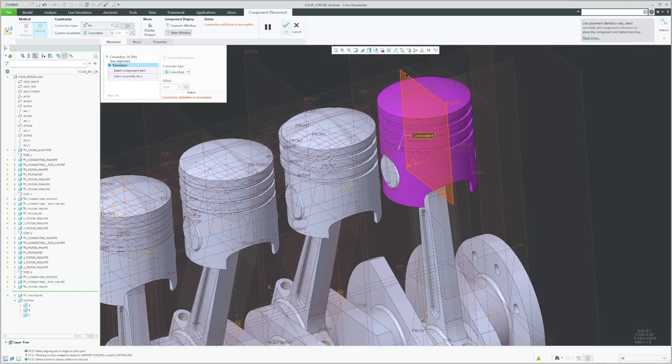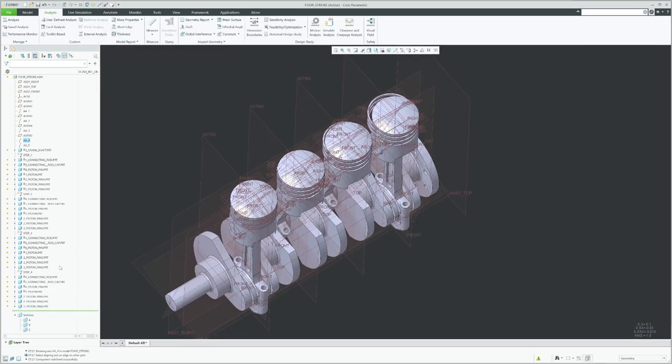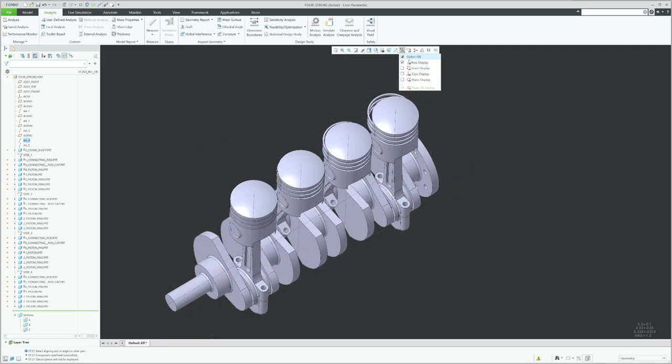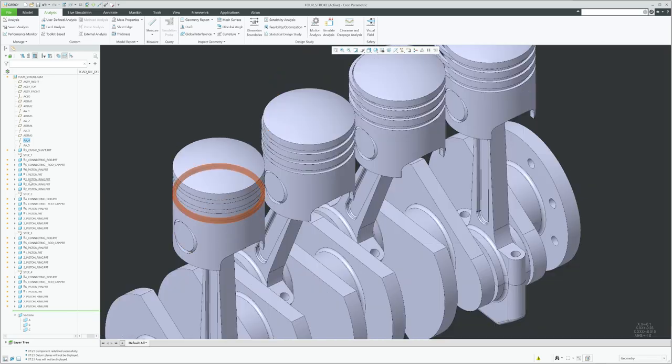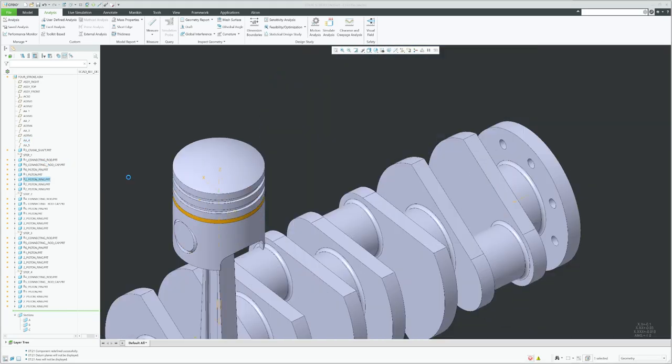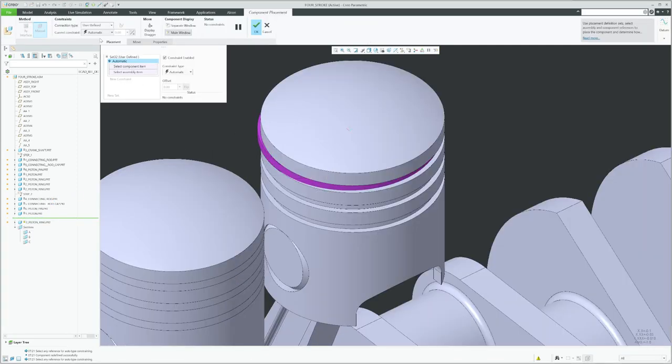Here it is. And we complete this with the cylinder, like this and this. There you go. Okay. So the most difficult part has been finished, so I will just save all this, and we just need to align the piston rings, sorry. Edit definition, this is correct. So let's go here, edit definition, general.